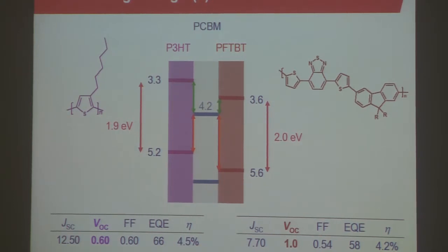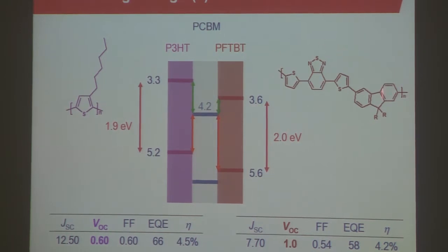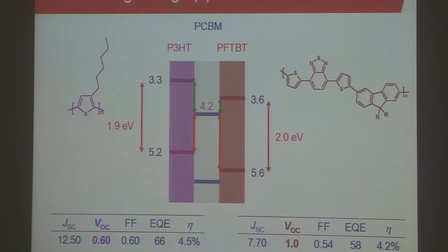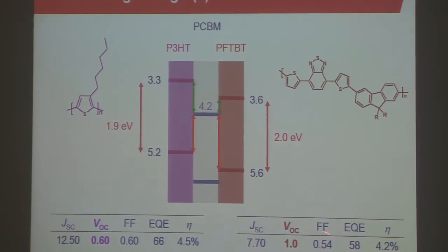The optical absorption spectra of the two systems are more or less the same. You just harvest a larger part of the energy. The efficiency doesn't really go up, and that is mainly due to the fact that the current goes down because of a lower quantum efficiency. And that is a bit problematic here. Also, these cells cannot be made that thick because the mobility is a bit less, and that puts the fill factor under pressure, if you like. So the fill factor is also quite a bit lower here, and that makes that this total cell doesn't help anymore.